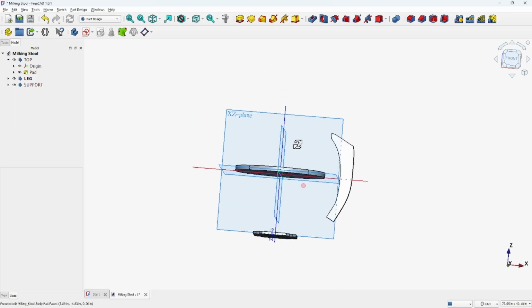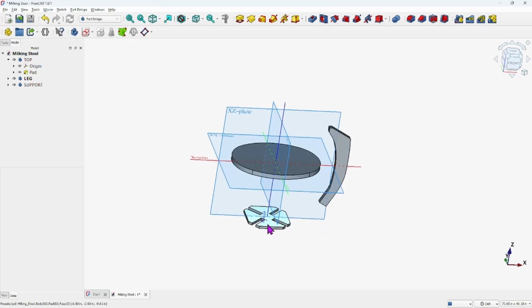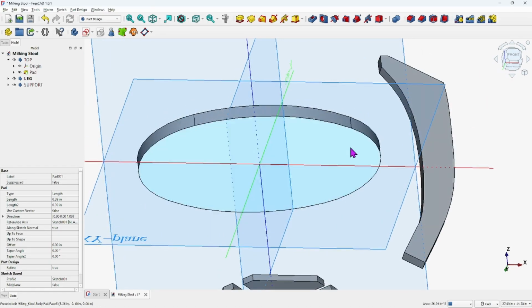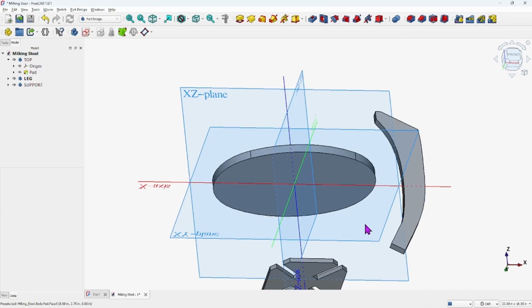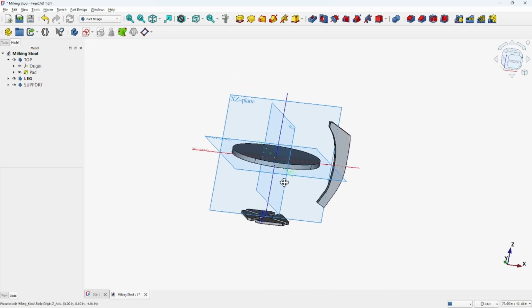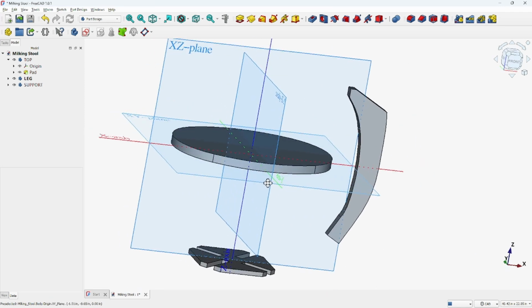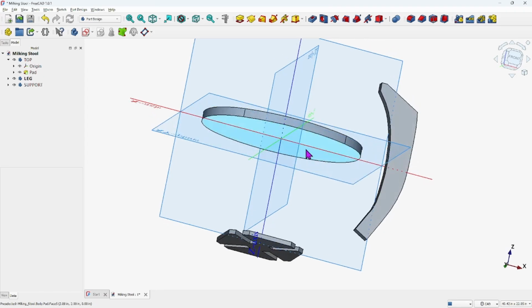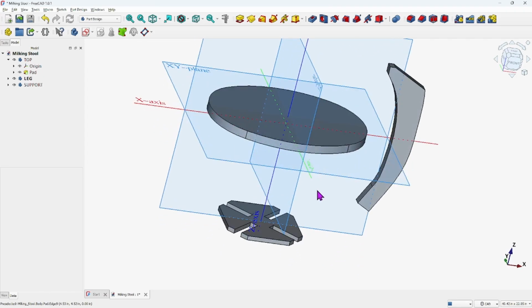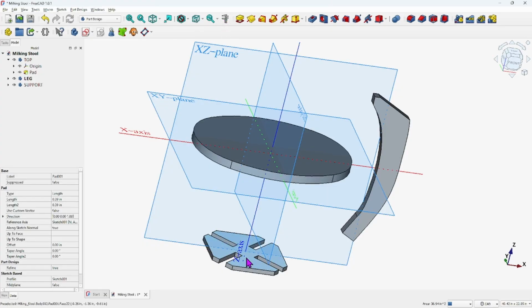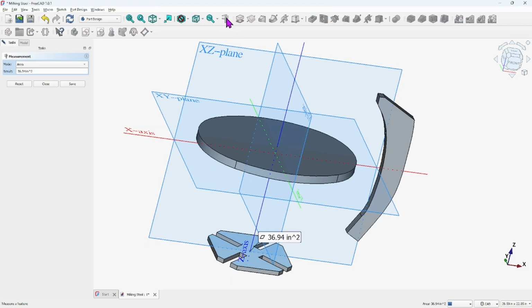All right. So what I want to do is get this top right here, that piece right there. See that? I want to get that flush to that piece right there. So how do we do it? I could use Assembly, but I'm so used to doing static models this way. I'll show you. I'm going to grab this surface and then this surface up here and then just get a dimension on it, and we're just going to set it to that dimension. So here's my dimension piece up here. Select that surface, use the dimension.